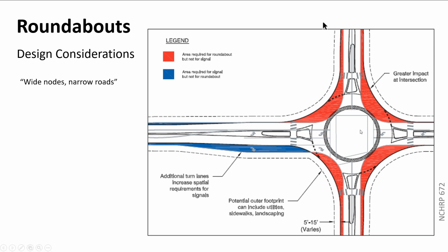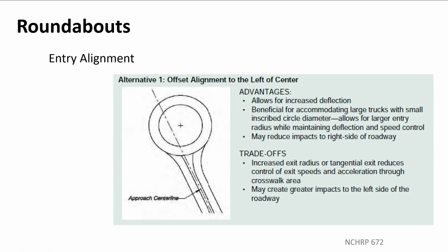So that's one of the things you'll hear about roundabouts. And in some states, for a busy enough intersection that would be a fairly big signal, it's been shown that you'd actually need more new area for all this widening of auxiliary lanes than you would from a roundabout. Or sometimes it comes out even. It's just that where you need it is different.